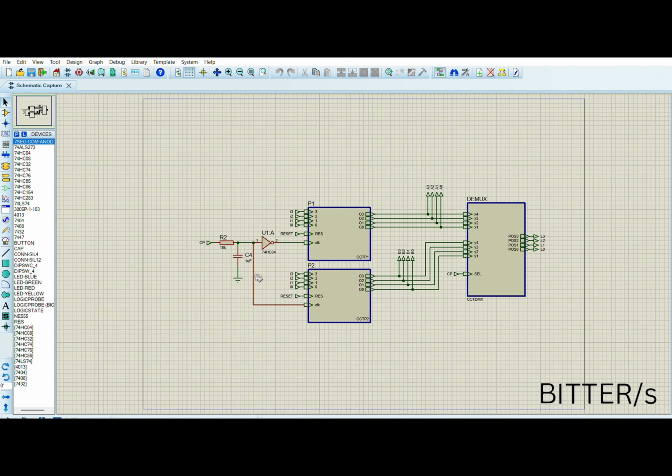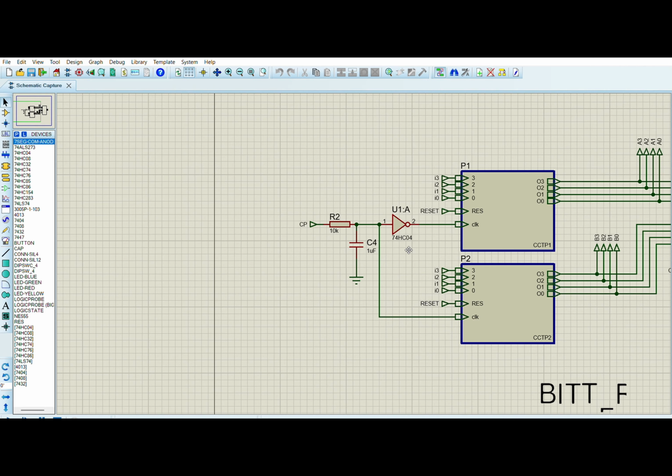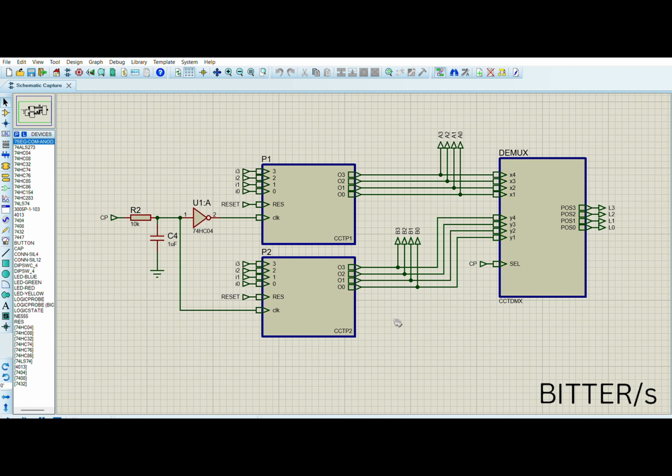The RC branch is added to calibrate the memory with the game. DMUX routes the stored player position to the snake ladder logic module based on selection input. The reset input allows resetting player positions to 0 0 0 0 when required. The circuit operates by updating the player's positions based on the output of the snake ladder logic module.